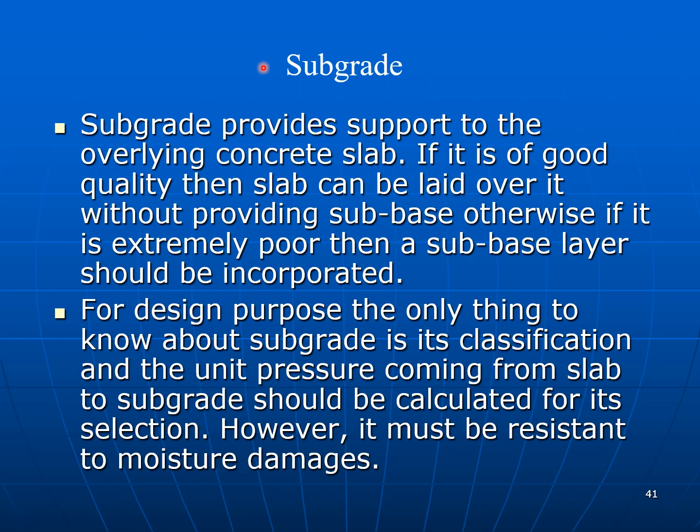Now look at the subgrade. Subgrade provides support to the overlying concrete slab. If it is of good quality, then the slab can be laid over it without providing a subbase. Otherwise, if it is extremely poor, then a subbase layer should be incorporated.